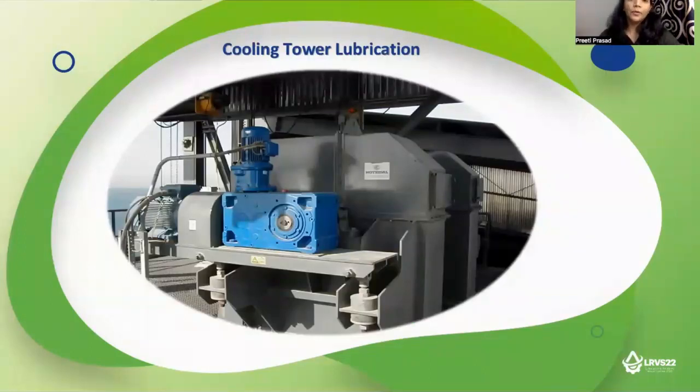Cooling tower lubrication. As you can see in the picture, the cooling tower system comprises two components, gearboxes and the electrical motor. Gearboxes are mostly single or double reduction gearboxes, having roller type gears or bevel gears, and generally oil splash lubrication or mist lubrication is found here.